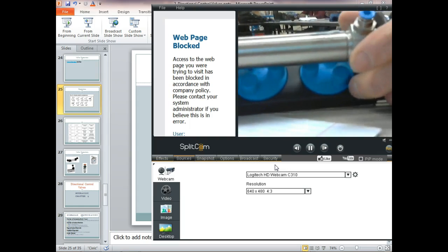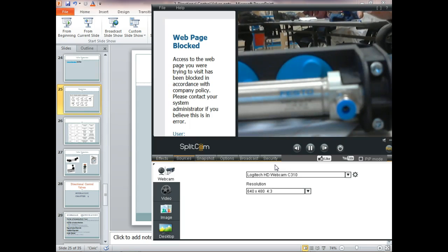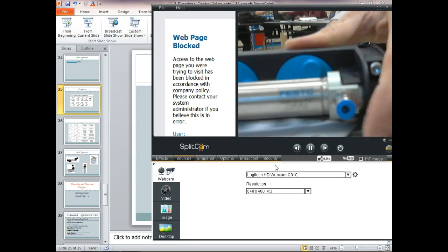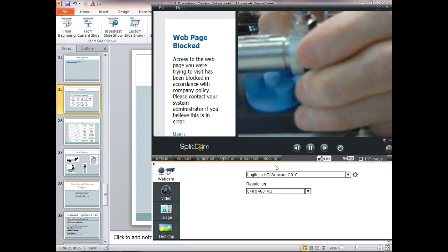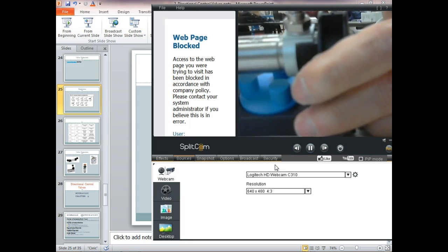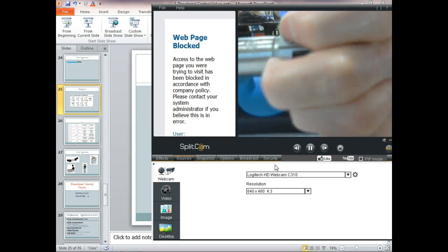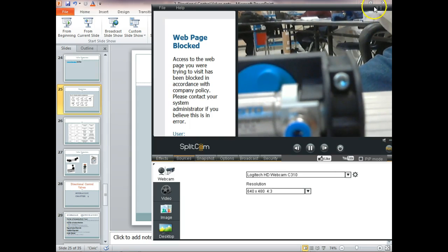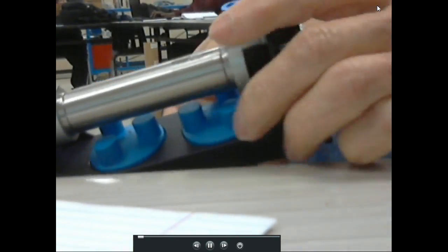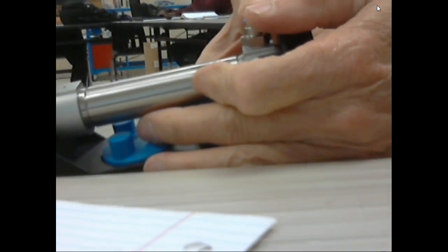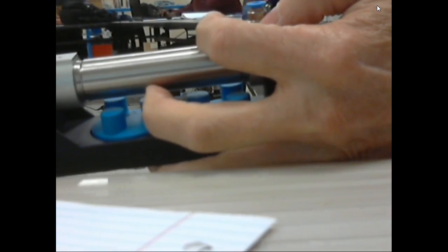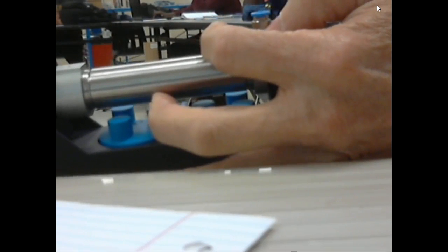This is the pressure port right here. What's nice about pneumatics is that we have these things called quick disconnects. We could screw it in, but on all ours we have what we call a quick disconnect. So this is a quick disconnect. I didn't bring any tubing over here, guys. But when you push the tube in, you push down on the quick disconnect, then you push the tube in as far as it'll go, and when you let it go, it'll latch it in. And then when you put pressure on it, it actually latches in real hard.